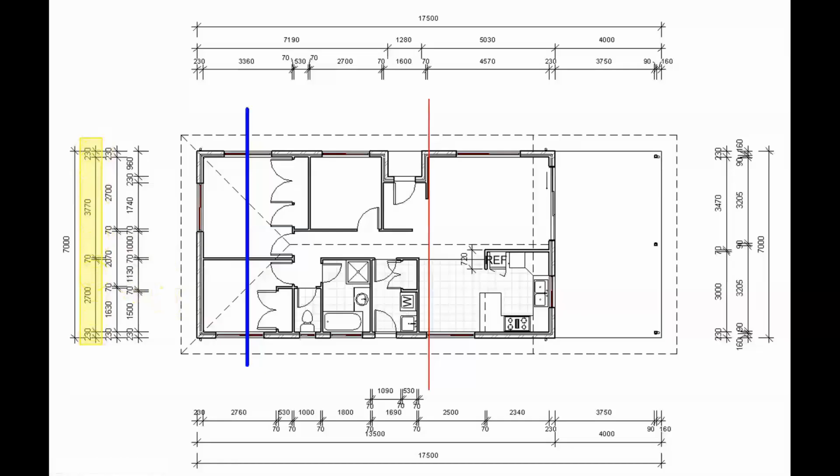And then on all sides of our project, the very, very final line of dimensions is always an overall dimension. It's like a double check. You put the overall dimension on this side here, and you put another one on the other side, and it confirms that everything that's being dimensioned between those two external points on both sides all add up. And it just helps with setting out of the project on site. So that's how this left-hand side of the building has been dimensioned.